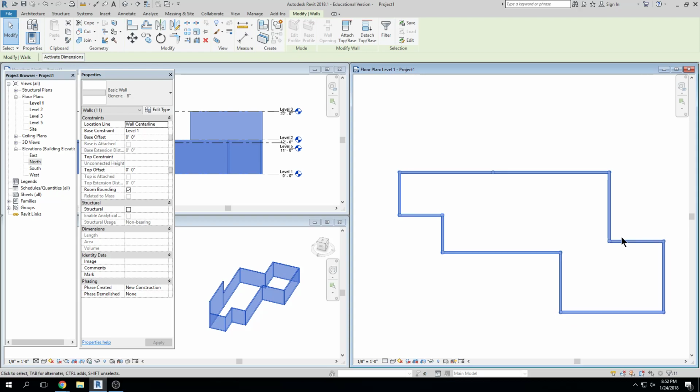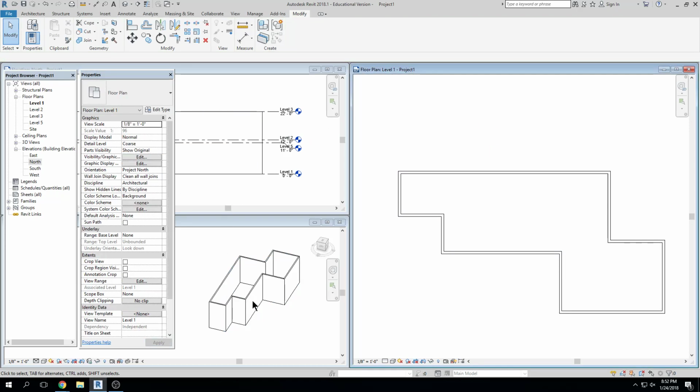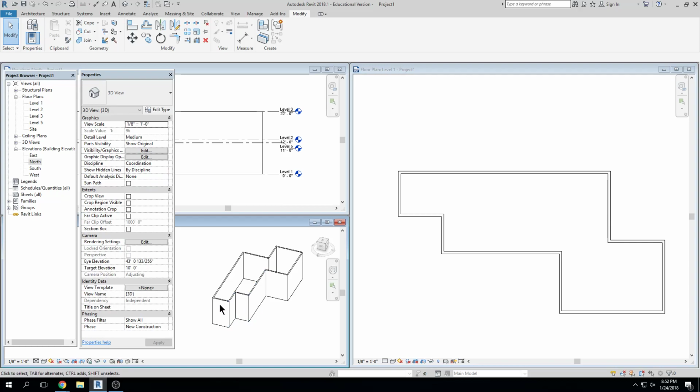They're our outside walls. I'm going to define these walls to go from level 1 all the way up to level 3. With that move, I've effectively defined my exterior envelope correctly, meaning it goes from here all the way up to where it terminates. That's our wall system.